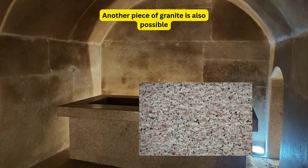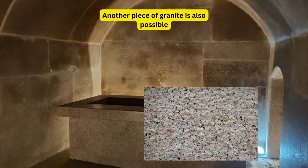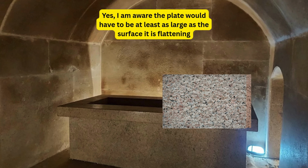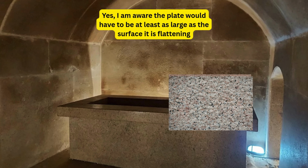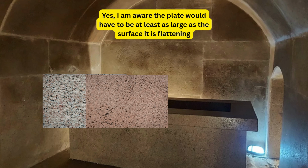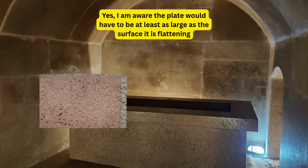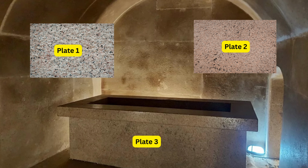The method would have to be modified somewhat because the plates would be the only possible moving portion, unlike the Whitworth method, where at some point each of the 3 plates needed to be immobile while the other 2 were moved. In any case, each set of 2 plates plus the workpiece would need to be rubbed together in alternating steps to make them all more flat. They couldn't have just used all 3 plates at the start, because when the workpiece was introduced into the rotation, it would be very far from flat and mar the known superflat plate.